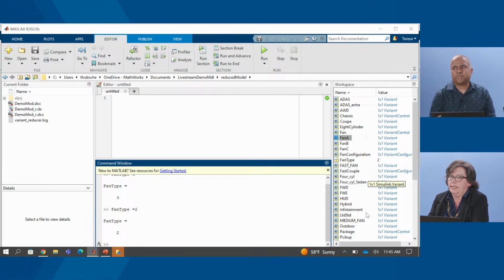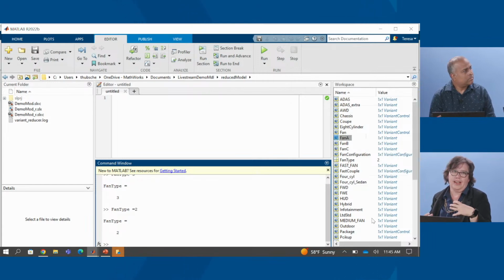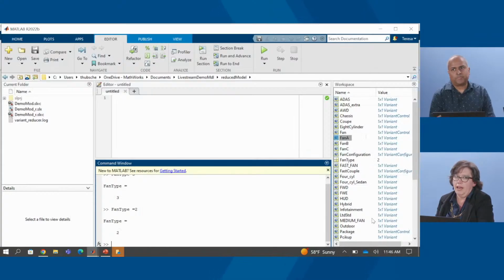Data dictionaries, if you don't know what they are, you might be confused because I think there's a dictionary and a dictionary type in MATLAB now too. Data dictionaries in Simulink are really different. It's essentially a place where you're holding your design data for Simulink. This would count as design data, variants, and capturing that and being able to package it in a project and manage your models and your data together. Data dictionary is something you probably should check out if you haven't already.